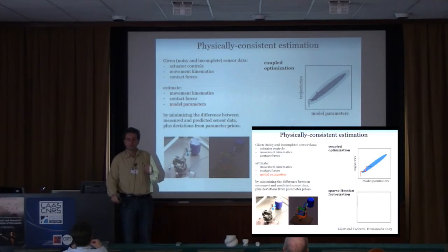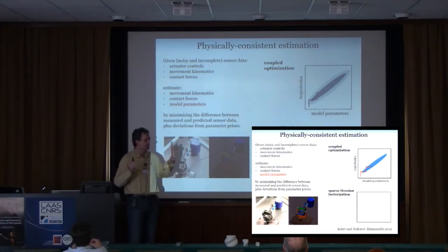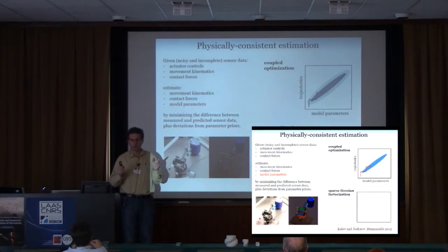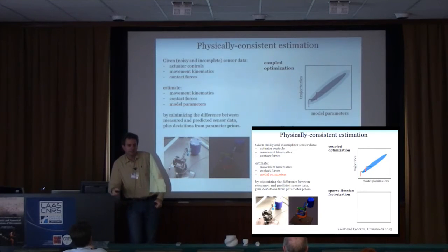So robust control is the idea that we're not going to optimize expected performance. What we're going to do is put some bounds on the disturbances or model errors and try to guarantee that if the physical system is within those bounds, then our control performance is going to be within some other bounds. And there are things called small gain theorems that tell you what's the mapping between the input disturbance and the output disturbance. And that's very good, except the only practical tools that exist, they exist for linear systems. Once you go to this general case, it's not clear what you can actually do, unfortunately.